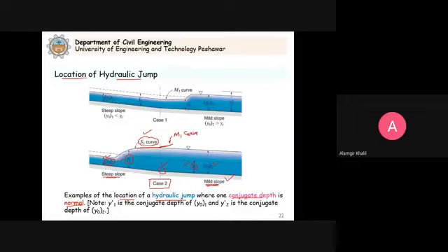Now, this M1 curve has to bring this depth to lower, because now at this point here you have this as the normal depth that we expect in the mild slope. So it means that this M1 has to bring this depth to this depth here.